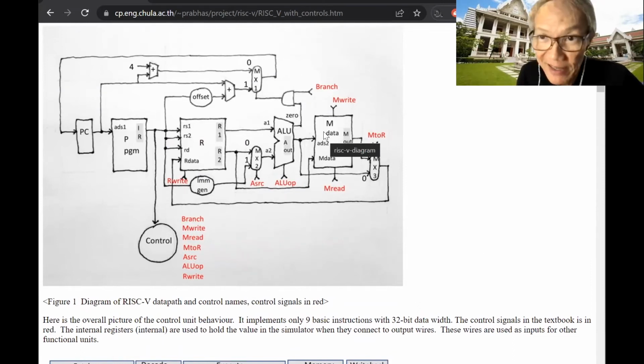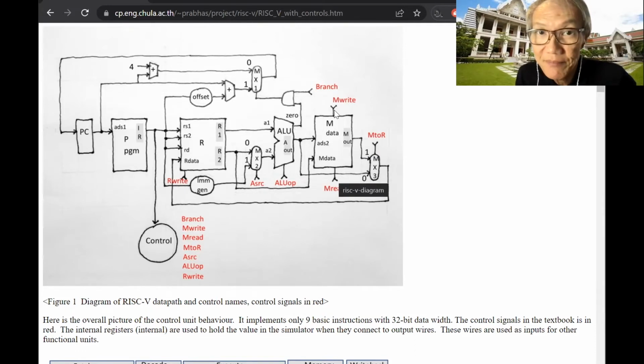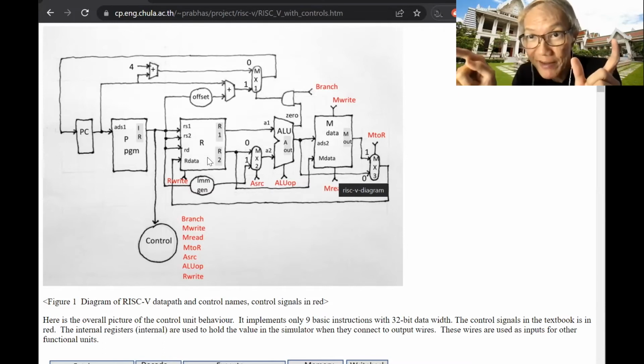We use the arithmetic logic unit. We can read one register here, and we can add it with the immediate value, selected by the source control here to choose the immediate value. It's just like add immediate, right? But now the thing we add is interpreted as the address. So we have the effective address here, and we issue the read. If we choose write, then the effective address is the same, and the data is wired directly from register number 2. Register number 1 is the base address for the load instruction. Register number 2 is the source register to be written to the memory.